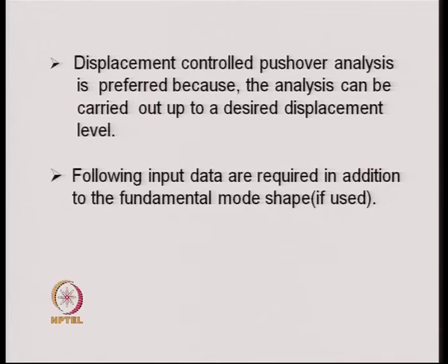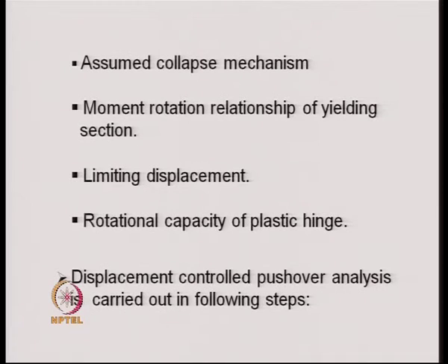Following input data are required in addition to the fundamental mode shape. So, as I told you, the loads are distributed along the height of the building according to the mode shape of the structure. However, it is not necessary that one should consider the first mode shape of the structure. One can assume any reasonable distribution also.